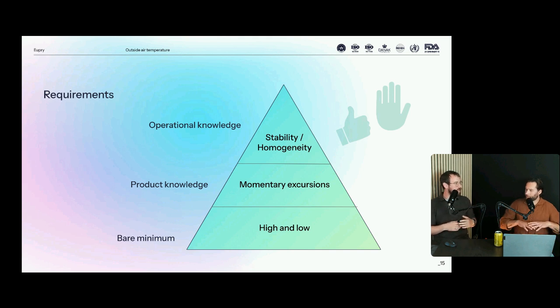So kind of the distribution of temperatures, exactly, both in terms of length and width in a warehouse, for example, but also in terms of height. Because that tells us something about whether our insulation is performing as it should, whether air circulation is as it should. So these are some of the points that will make an auditor clap their hands and say, well done, but I don't think it's required.